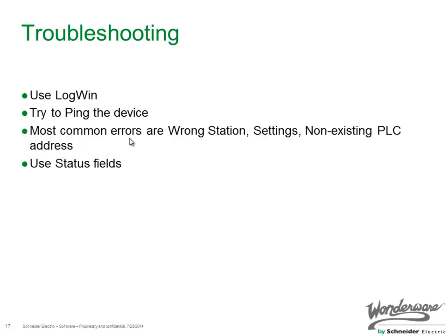It's highly recommended that you use those status fields, and then as I mentioned previously in the video, use a unique address or possibly an array of addresses for each of those status fields in each of the different main driver, standard drivers, and then across the multiple standard driver sheets that you could have to help you try to troubleshoot. It's always a good idea to cut the problem in half.